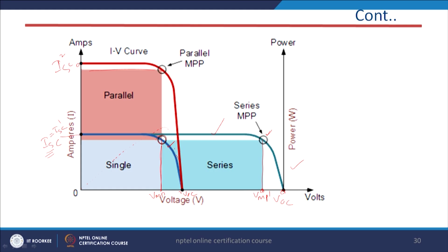Now, this is the VOC point, this VOC is equal to VOC 1. And what about the maximum power point? That point also shifts to another. Does it shift? No, it is the same as our previous maximum power point, here it is. So, only the magnitude changes. The voltage VMP remains constant, I short circuit changes and V open circuit remains constant for this.